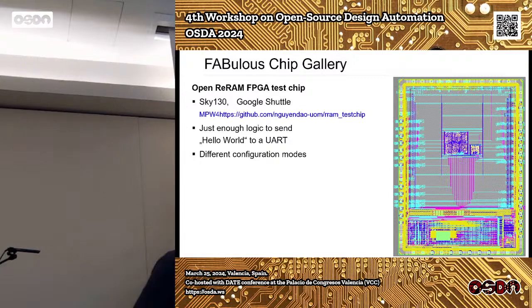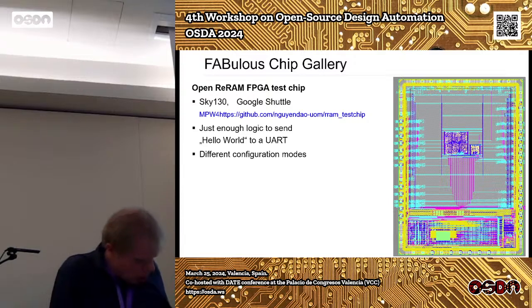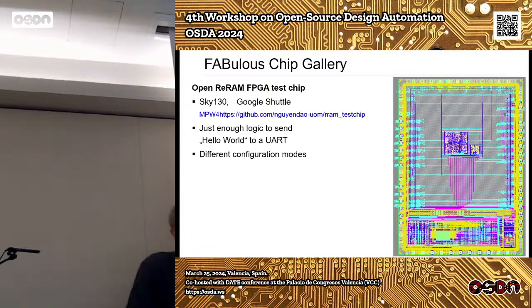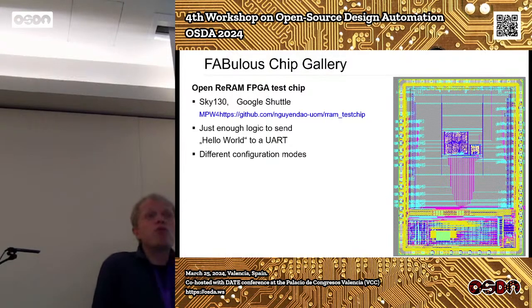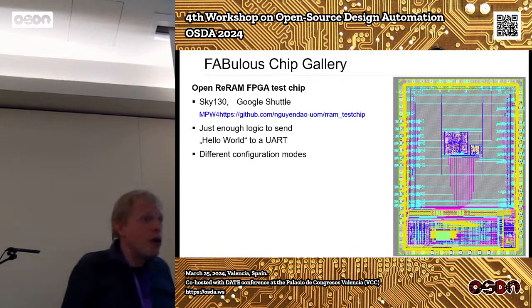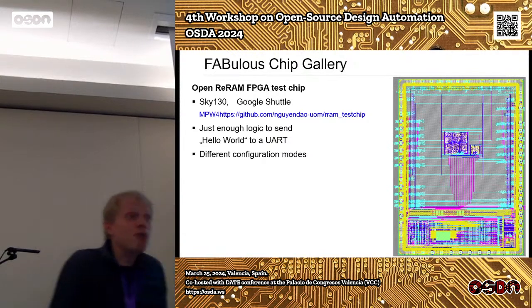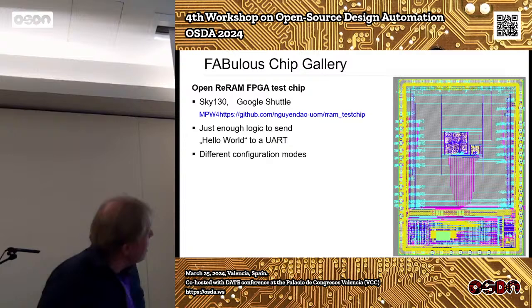Our first configuration storage here is not SRAM cells, we use basically memristor cells, and use a voltage divider. So I have 2 memristors for each memory bit, and one of the memristors will always be on low resistance. This draws a little bit more current, we know that, and this is why we haven't filled the chip, as we want to have a chance to bring it up without frying something instantaneously.